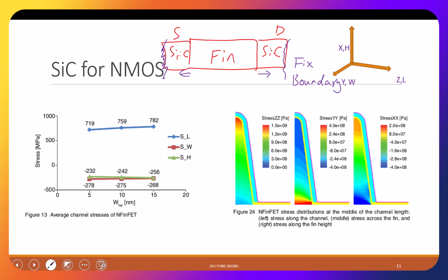No, though, when the carbon is incorporated in the silicon, I mean, it depends on what you mean by dope, right? Usually when we say doping, we try to add the donor or acceptor so you become active, right? You can donate electron or hole. But carbon and silicon, they are both valence equal to 4, right? So you don't have this electron or hole, donor or acceptor, but you do put them there so that they